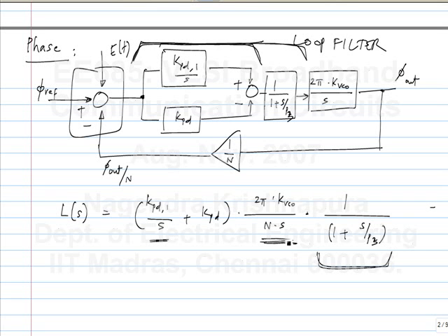So what will be the E of t? It is 0, right? Because the type 2 PLL will lock with 0 phase difference between the inputs. If you have 0 phase difference between the inputs, the up and down pulses will be infinitesimally small pulses. So we came up with the type 2 PLL to improve the type 1 PLL, but it also in steady state reduced the reference feed through to 0.